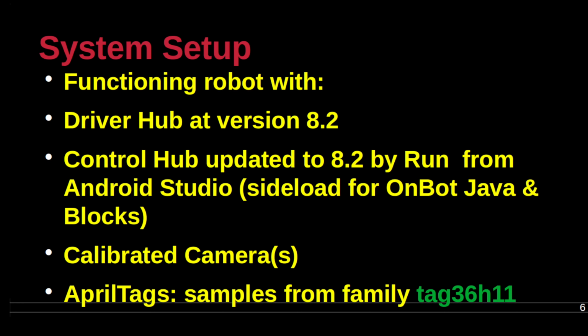The camera connected to the Control Hub must have been calibrated previously. As mentioned in a previous slide, Logitech and Microsoft webcams have been calibrated by FTC, but other webcams will require independent calibration. While one can detect the identifier of an AprilTag, the pose estimates will be inaccurate if the calibration coefficients used by the AprilTag processor are not those for the webcam in use.